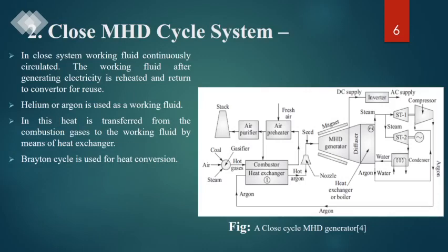So that ionized gas we utilize in some other use. For example, we can pass it through a turbine and compressor and use it for rotary work, rotation of a shaft, and transform it into other mechanical work. We can use it as a preheater. You see this flow passing from this compressor, and after argon seeding from here, again we bring it into the heat exchanger, and then from here we use it. So this is a closed MHD cycle.